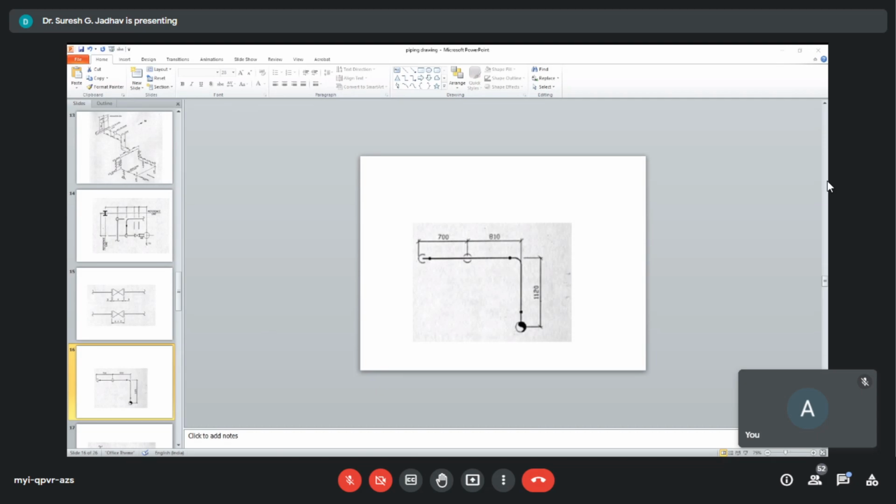And then draw the dimension lines unbroken with fine lines, right? Write the dimension just above the horizontal lines. Here you can see it. For vertical lines, write it sideways. These are the rules for writing the dimensions, and the dimension lines can be terminated with arrowheads or oblique dashes. So here we can see the arrowheads or oblique dashes.